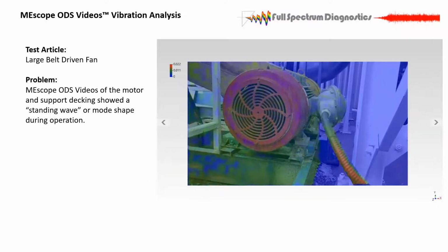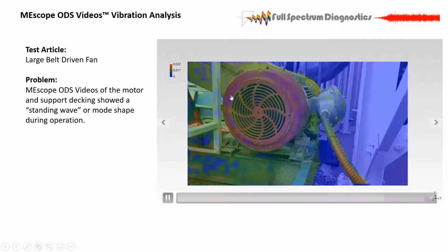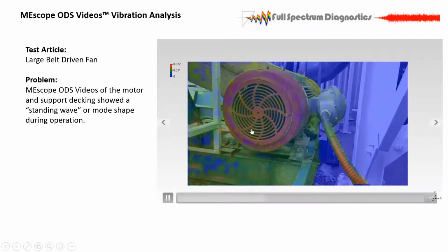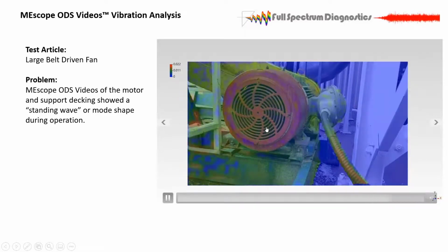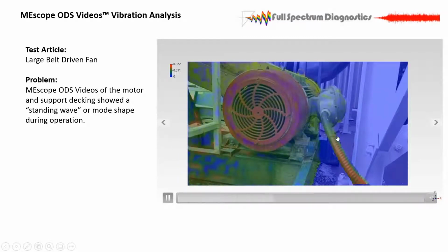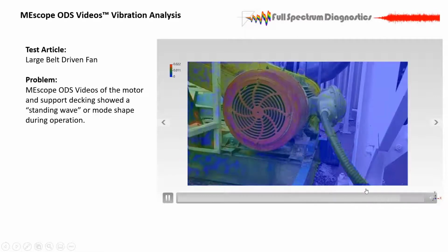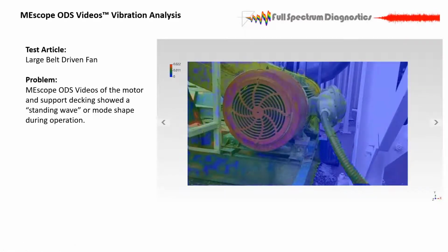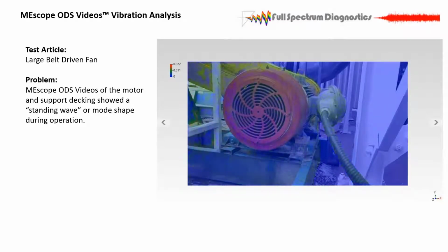And put a little color on it. You can see where stuff's really moving. So there's a couple of orange spots on the housing here, and it's kind of sheet metal. We don't want to take vibration if we're looking for bearing defects and things like that, but a lot of sheet metal response and cabling. In this case, the connection for the motor was bouncing around. So it's nice to have a color contour format to see what's going on as well.